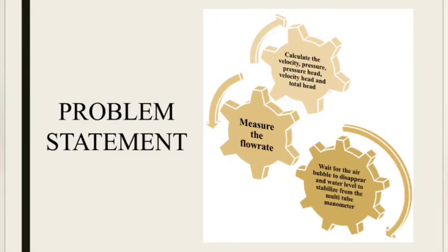The first problem statement that occurs for us is that we have to wait for the air bubbles to disappear and the water level to stabilize for 10 to 15 minutes in the multi-tube manometer. Secondly, we have to measure the flow rate. And lastly, we have to calculate the velocity, pressure, pressure head, velocity head, and total head.